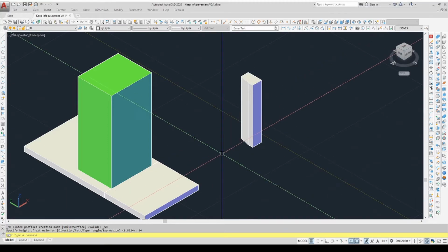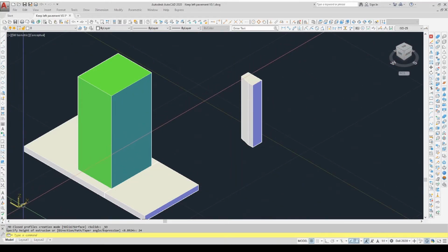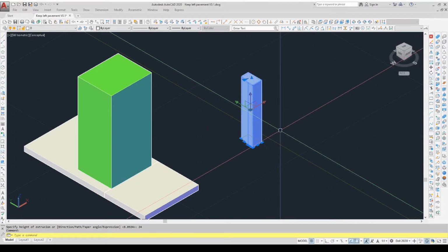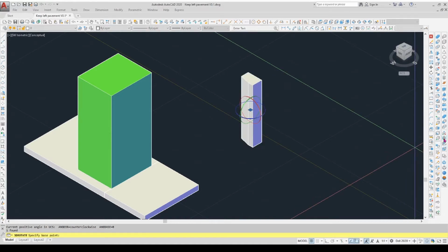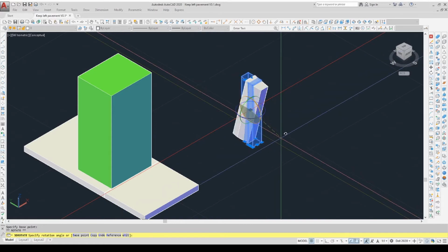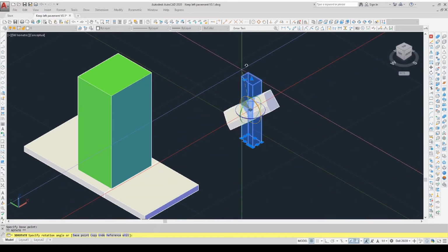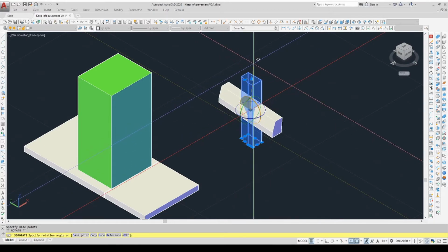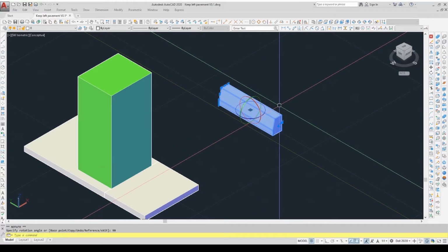Unfortunately, because we're using the XY plane, which is on the bottom if you like, it's decided to make it vertically, so we need to reorientate it. We use the 3-dimensional rotation command, which now is asking me which plane do you want to rotate it in. Whichever one I touch changes colour, and I want to use the red one, so I'll touch the red one, and it's now asking me how far round in terms of angular distance do you want to rotate. We'll hazard a guess that it's 90 degrees, so I'll type in 90, and yay, got it right.